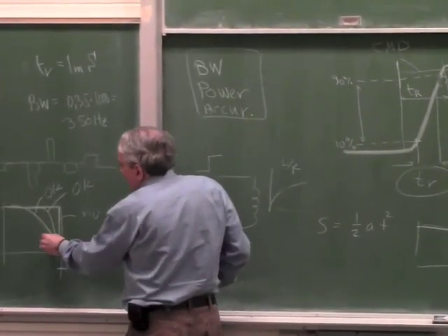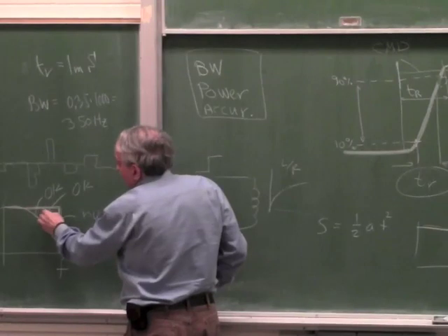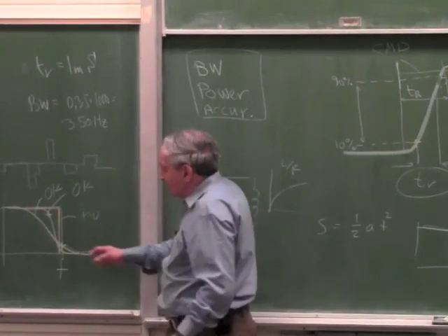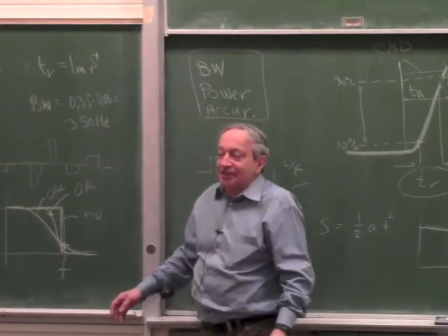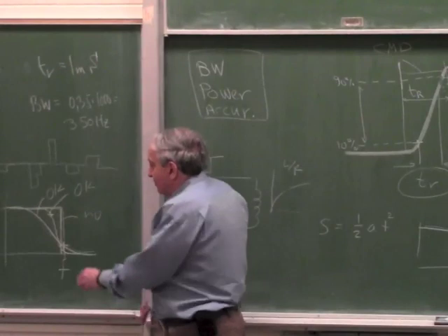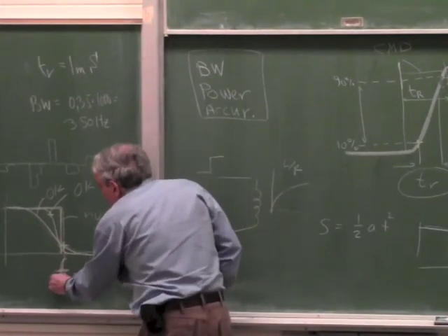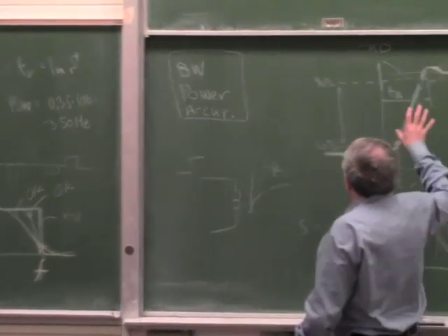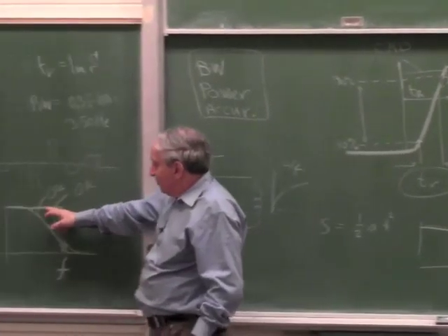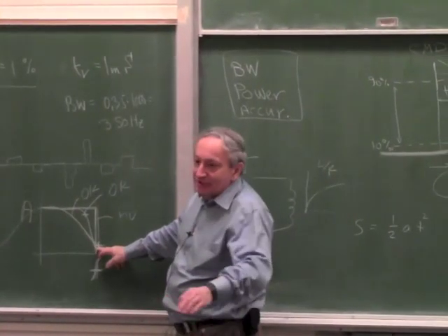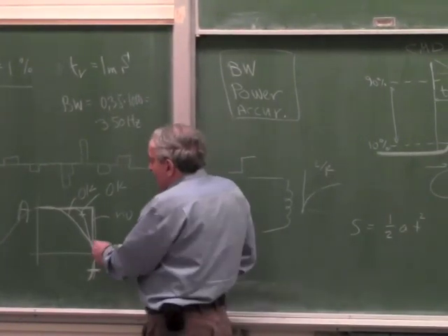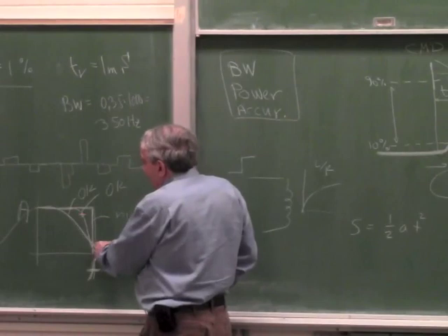Okay. Now, I also spent time explaining how do you calculate the cutoff of the filter. Like, if, say, a filter has 2 points, a 3 dB point, and say a point where it transmits X percent, 1% or whatever. Because the filter itself, in the frequency domain, is defined a little bit similar to the way this is defined in the time domain. Like you say, okay, it starts dropping from here and it drops to minus so many dB here. So how do I calculate these points of the filter?